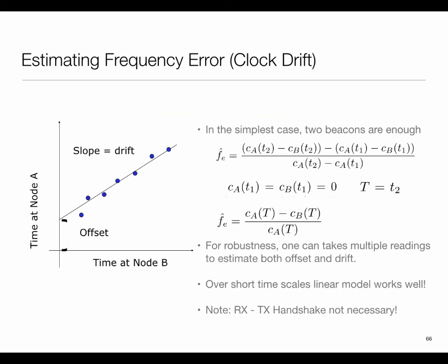So kind of the idea is that if I were to measure this offset, I'll get some measurement points about my offset, and then I would do some sort of curve fitting over it. And if this is over a short enough time interval, that is, I'm doing these measurements relatively rapidly, then a very reasonable assumption to make is that the drift is constant, or that the drift is changing linearly, which is the more typical arrangement. So basically you do a straight linear regression over a time window.